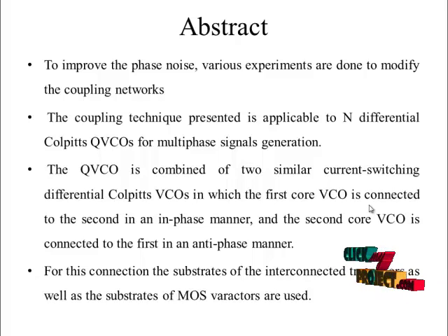In conventional cross-connected LC VCOs, the noise generated by the active components perturbs the VCO output at its zero crossing, that is the maximum noise sensitivity point. On the other hand, in a Colpitts oscillator, the maximum noise level, that is the maximum of the impulse sensitivity function generated by the core transistor, is aligned with the minimum oscillator sensitivity point. Thus, Colpitts oscillators have superior cyclostationary noise properties and, as such, potentially a better phase noise performance compared to the